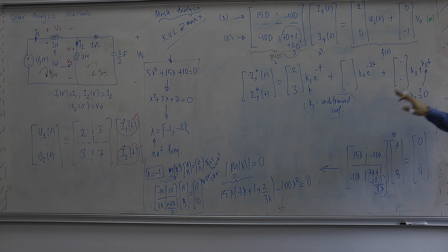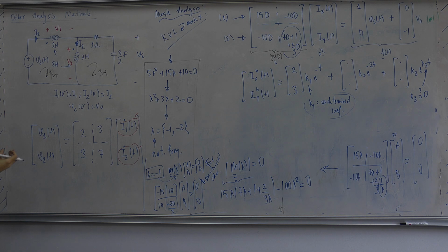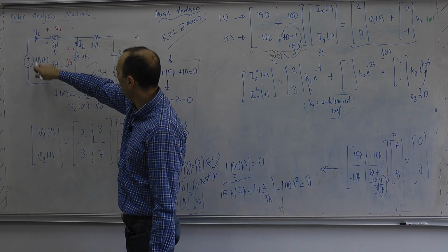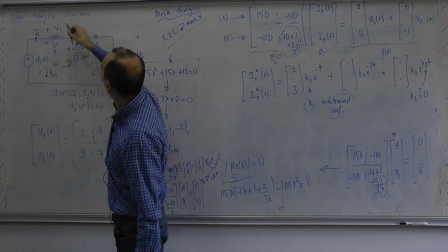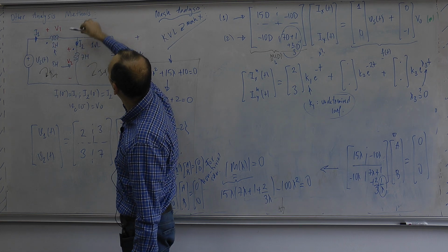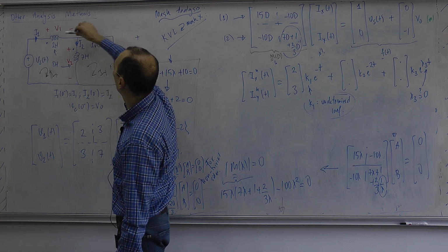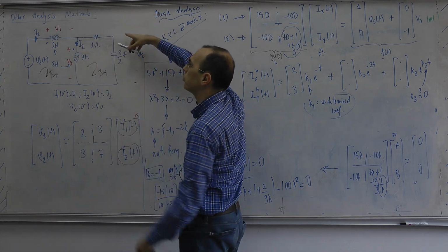You should be careful in mesh analysis, similarly in node analysis. There can be some natural frequency lost in your analysis. So how do I decide on this? Well, again, I check the order of this circuit. One other way of checking the order of the circuit is to assume the 0 input case. Then, can you set this initial condition like 5 amperes? I can set this one as 4 amperes. Then there will be 1 ampere going this way. Okay, this is equal to 0. I'm just talking about the initial conditions.